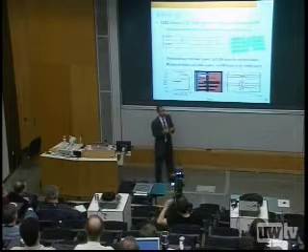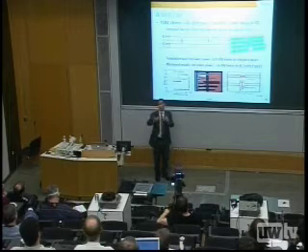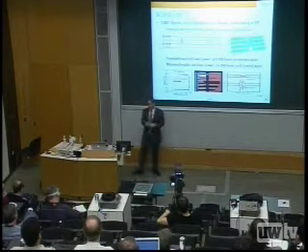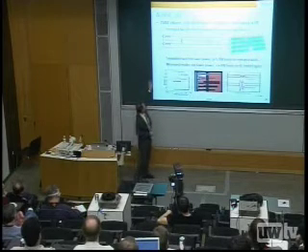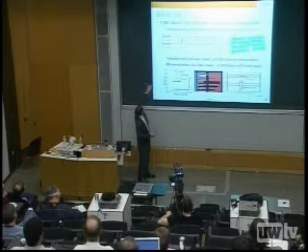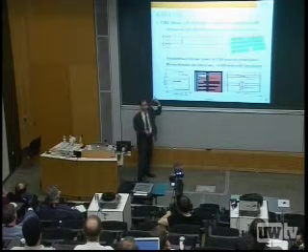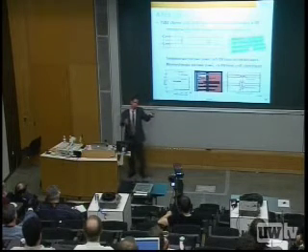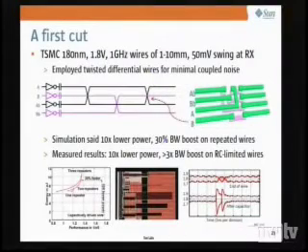Now, if you do this, you better make sure you don't have noise issues, and so we twisted differential wires. This is an idea that's been known in telephony for about 50 years, and so it's nothing profound, but we did do a twist of A and A bar and B and B bar. And if you twist them as shown this way, you can avoid Miller effect capacitance, which in fact saves you more power. The cost of a twist is relatively small. Here's a picture from our layout tool. We just did a 3D rotation, and it's just a few via pitches and another wire layer.